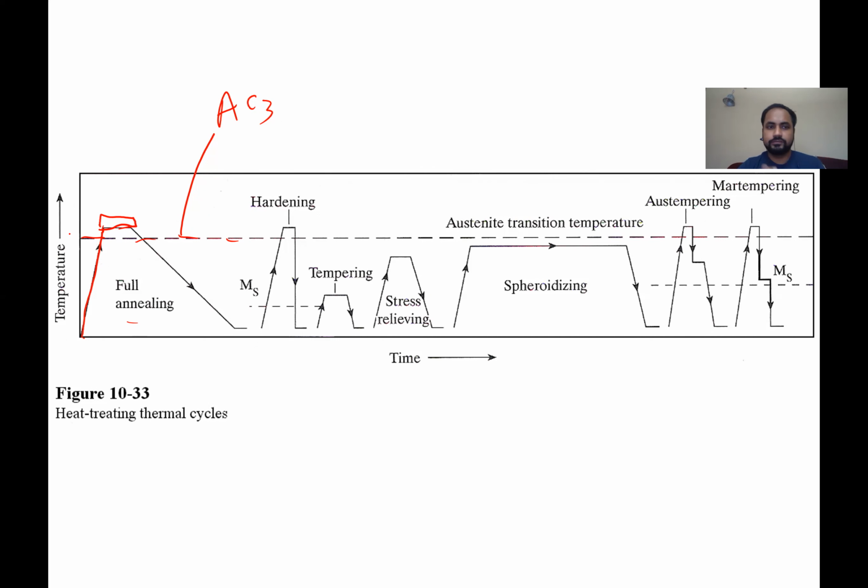In general, industry uses, I think, like 1 inch per hour of heat treatment, something like that, depending on the material. So if it's 1 inch thick, they would do the heat treatment for an hour, or depending on the thickness. And it depends what your end goal is. So it varies. Then once you have reached above AC3, if you do a slow cooling, there are 2, 3 kinds of slow cooling that you can do.